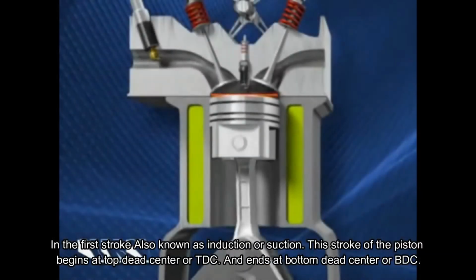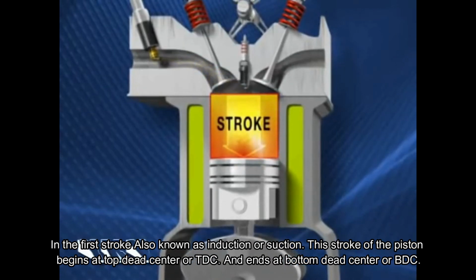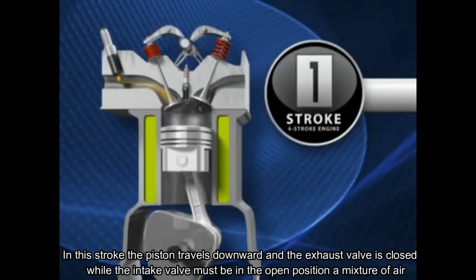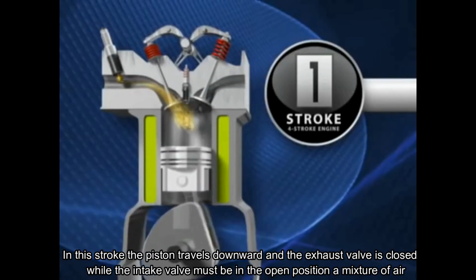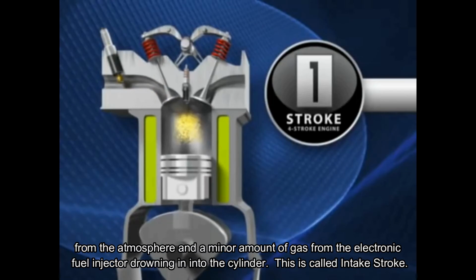In the first stroke, also known as induction or suction, the piston begins at top dead center or TDC, and ends at bottom dead center or BDC. In this stroke the piston travels downward and the exhaust valve is closed while the intake valve must be in the open position. A mixture of air from the atmosphere and a minor amount of gas from the electronic fuel injector is drawn into the cylinder. This is called the intake stroke.